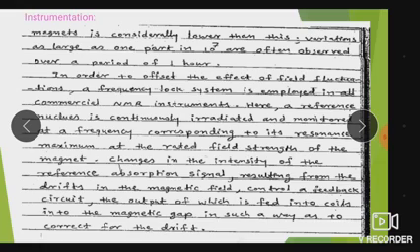So the alternative method used in the instrument is the reference cell, where the sample is continuously irradiated with a stable frequency and monitored at the related field strength of the magnet. Changes in the intensity of the reference absorption signal result from drifts in the magnetic field. The control feedback circuit, the output of which is fed into the coil in the magnetic gap,